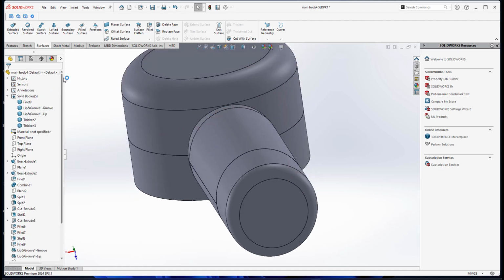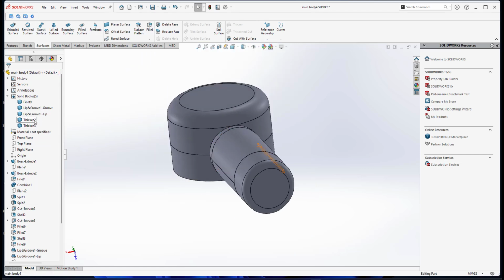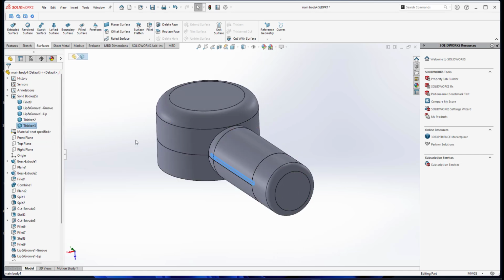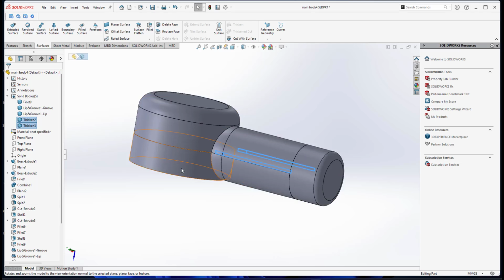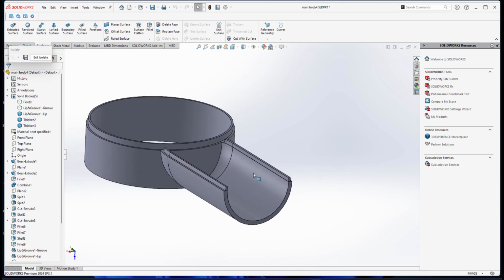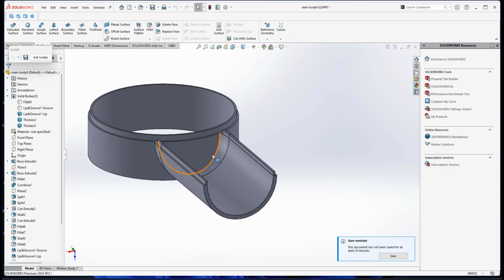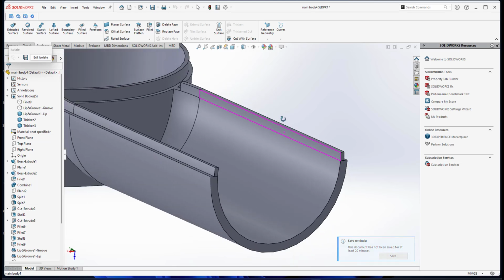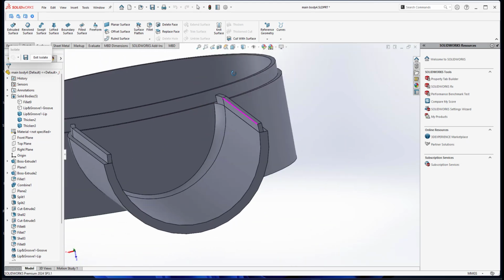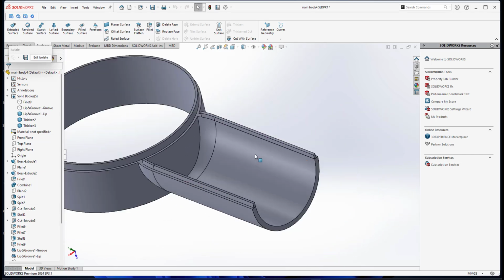all right. So now I have 1, 2, 3, 4, 5 solid bodies. Thicken 1 is the rear lips. The thicken 3 is the front lips. I select these two ribbons, two lips here, and also my front body. I isolate it. As you can see now, I have a lip for the front casing. I need to join it. Later I will show you how I will join it, since these are still three separate bodies. So this actually will be the lip for the handle.